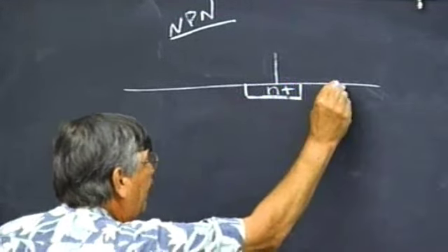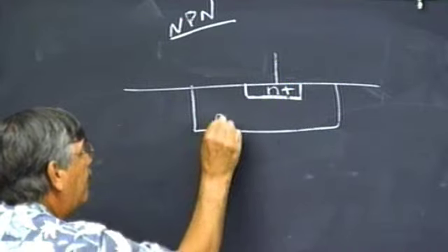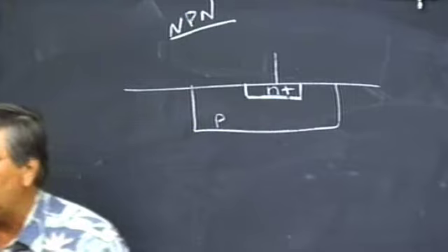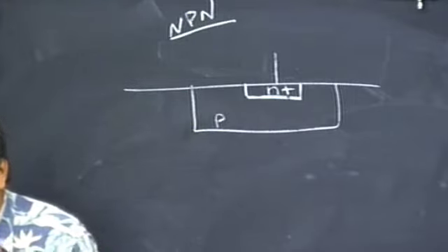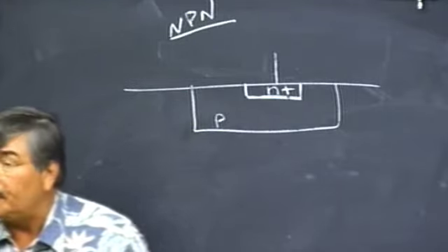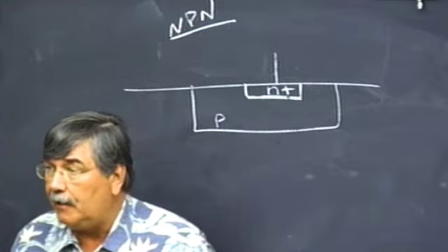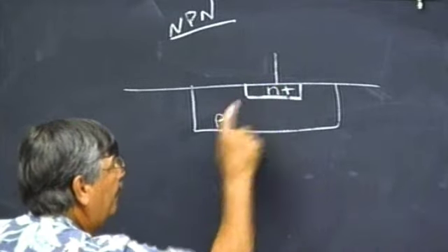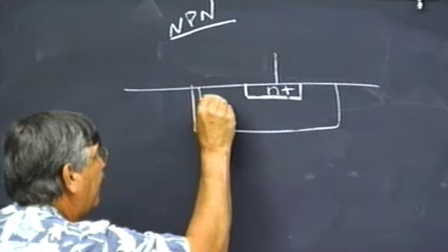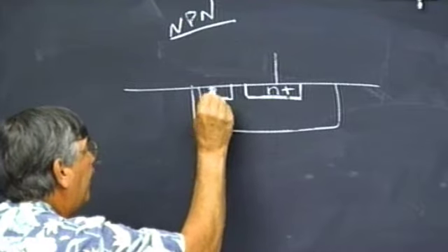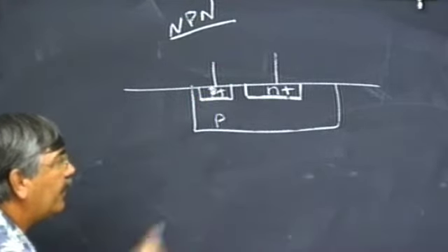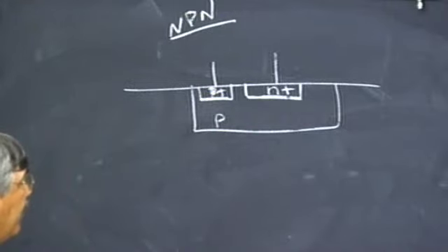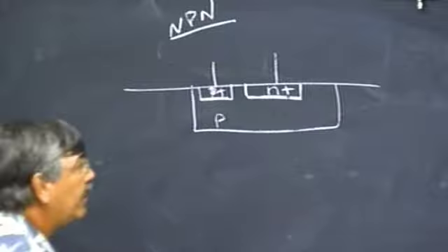Then that is diffused down inside an existing layer, which is moderately doped p-type, which is the base. I need to tell you that it's very difficult to make a good quality non-rectifying junction between a semiconductor and a metal unless that semiconductor is extremely heavily doped. So we can make a metal to N+. To make a metal to P, we need a P+ region in here, and so there's our base contact. So it has to be heavily doped to avoid problems. We don't need to talk about the problems. Maybe we can later. Actually, we can exploit those problems sometimes.